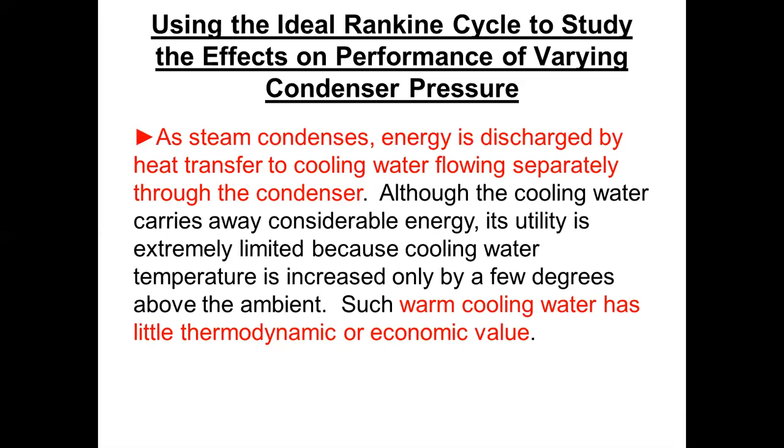It's a lot of heat that gets transferred, but because of the low temperatures involved in the steam condensing and the condenser water into and out of the condenser, there's not much opportunity to recover it. If you recall from your second law analysis, low temperature energy doesn't have much potential to do useful work. High temperature thermal energy has tremendous potential. And so as we degrade that energy by taking it to a low condenser pressure, we make what we reject from the cycle pretty much worthless for any practical application.